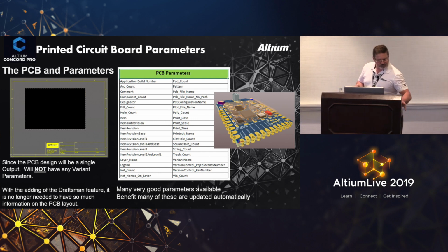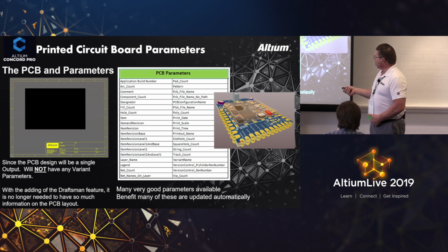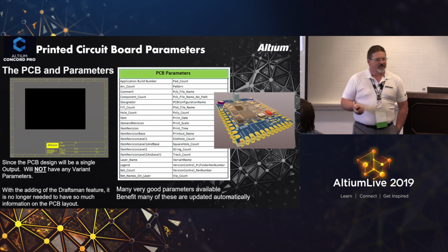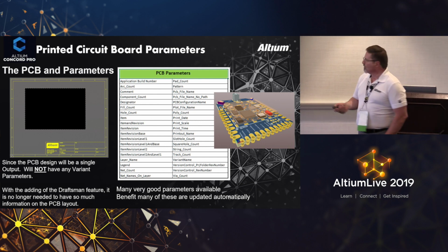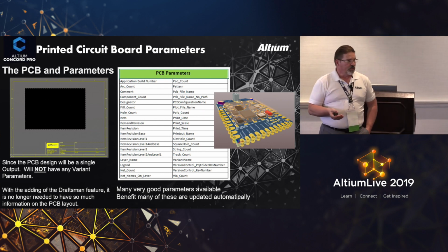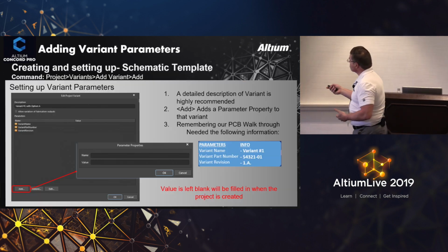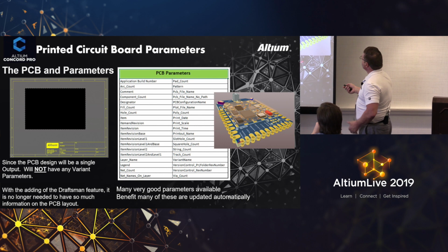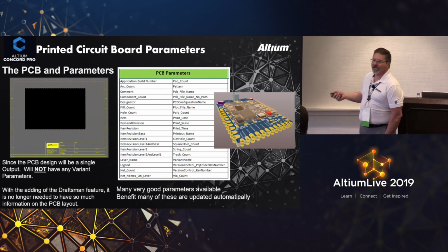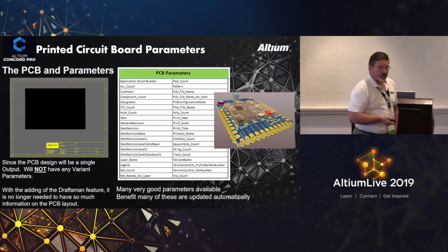When we were working with SVN, that would be the version control folder number and the version control revision number. We could pull those numbers in and use them as parameters on our schematic sheets and our PCB. That's what this number is on our board, 3928. It was a revision control number that we dropped in there.